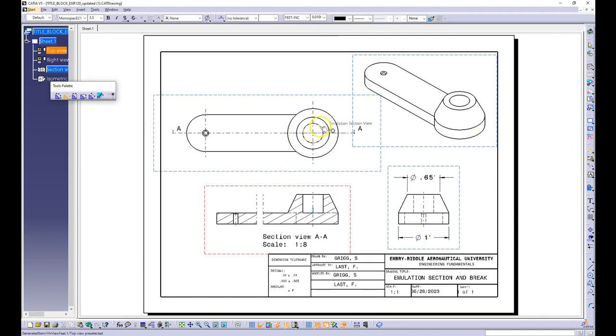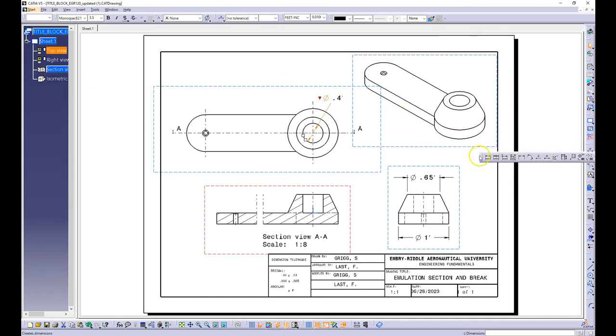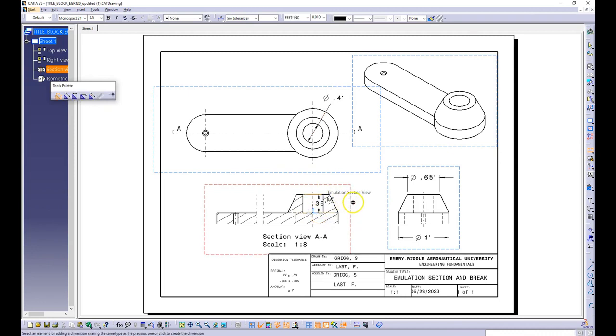And then I'm going to do my subtractive cylinder on the side where it shows as a circle. I will need to update the properties there, but for now, let's go ahead and select the length dimension to set the depth of the hole, or the pocket rather, because there's not a tapered end like you would see from a drill. And then we'll add our thickness, also with a length dimension.